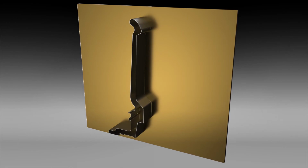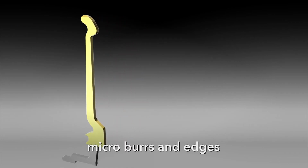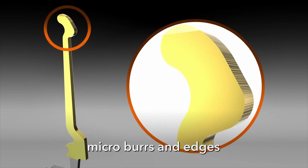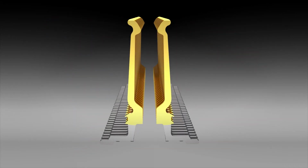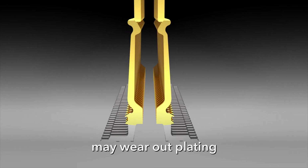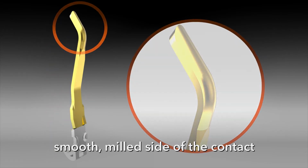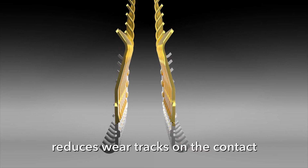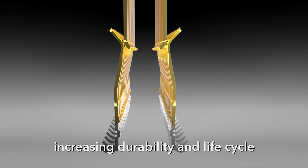With some connectors, the mating edge of the contact is the cut edge of the pin. If you look at the edge under a microscope, you may see micro burrs and edges. This reduces the life of the connector because repeated cycles against those cut edges will wear out the plating. But the mating surface of the edge rate contact is the smooth, milled side of the contact. This smooth mating surface reduces wear tracks on the contact, increasing the durability and life cycle of the contact system.